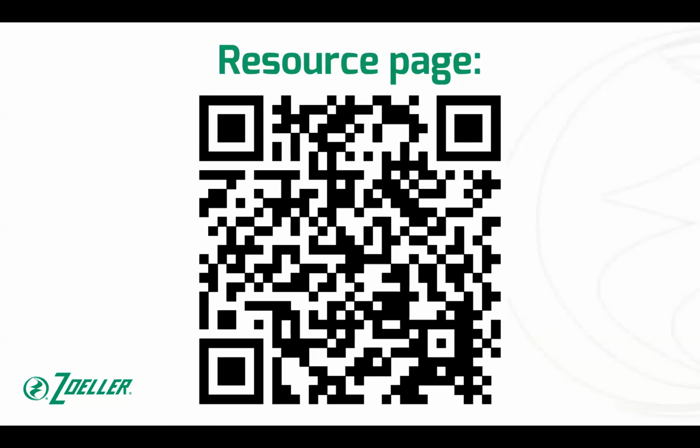Yeah, it wouldn't be a real integrated, here's specifically what the alarm is type of situation like it would be with our cloud. But you wouldn't even need the gateway. All you would do is connect to our dry contacts. On a duplex, there'll be 3 dry contacts, 1 for each pump. So you get your pump run dry contact, and then there's an alarm dry contact. All of the alarms go to that single contact, and that contact changes position if there's an alarm condition of any sort, which probably has occurred to most guys hearing me that, oh, that means I don't know exactly what the alarm is, but I know there is an alarm.